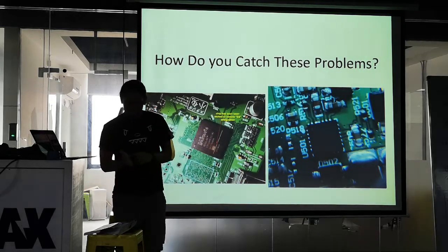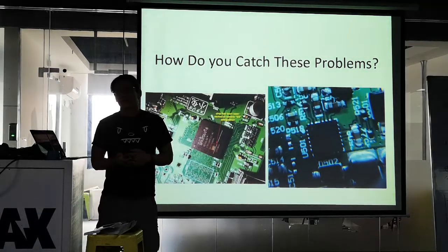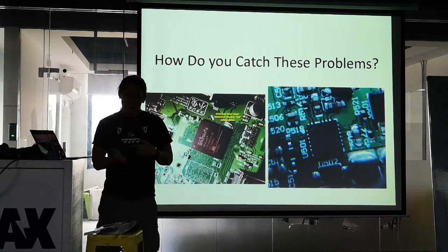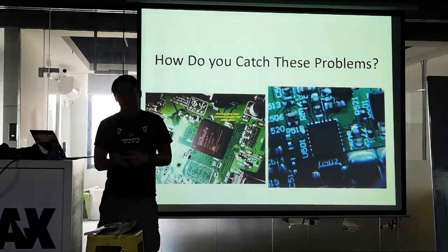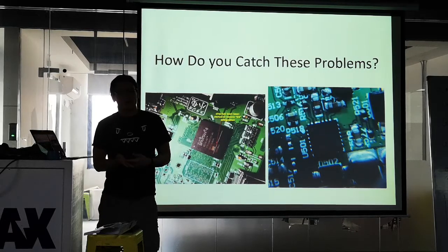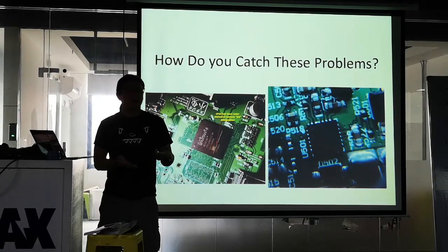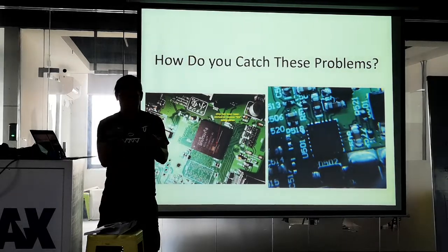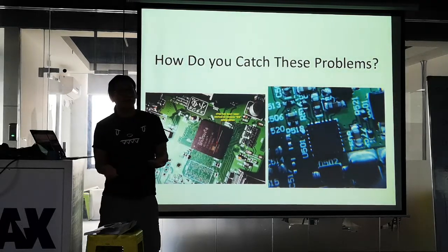And it turns out that underneath that white rectangle used to be the letters ES for engineering sample. What happened was someone in the distribution chain had laser etched off the ES, the engineering sample marking. These were pre-production silicon that Xilinx made, handed to partners to validate that the FPGA worked, and they were meant to be thrown away after that process. So in many applications that didn't care about the things that changed between pre-production and production, many users may not even notice that change.